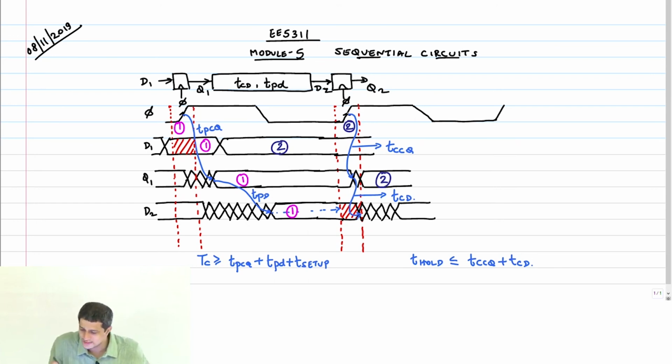Now we said that there can be skew in this, and by the way, skew is not just the positive edge moves, the entire clock will move. There is a phase shift between these two clocks. If only one edge randomly moves, which means the time period of that particular thing comes down for that moment, then that's called jitter.